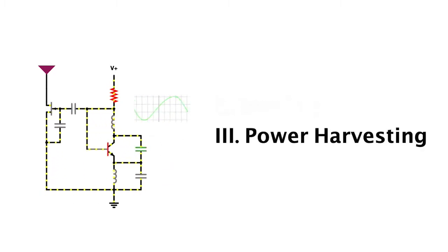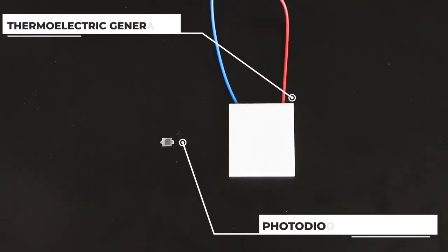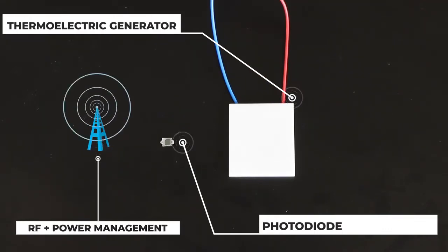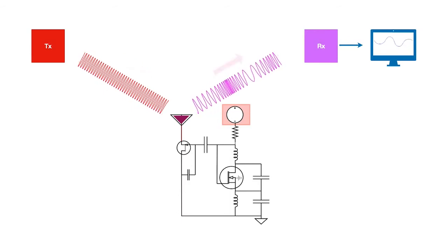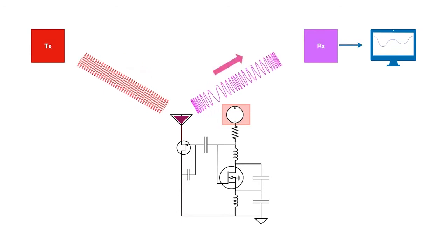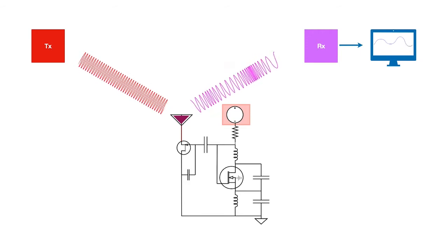The low startup voltage and current of our oscillator enables simple power harvester setups with no power management. In fact, a single resistor is used to match the harvester power supply to the requirements of the circuit. Power harvesters include DC sources like photodiodes, TEGs, etc., or in the future, AC sources like RF with some added power management. A plain carrier wave that then strikes the antenna is backscattered, modulated by the antenna impedance. This is received by an RF receiver and demodulated to extract sensor information.